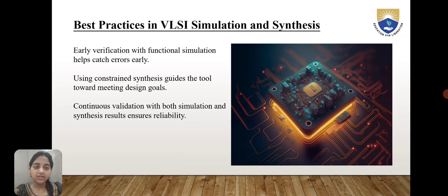Best practices in VLSI simulation and synthesis. Early verification with functional simulation helps catch errors early. Using constraints in synthesis guides the tool toward meeting design goals. Continuous validation with both simulation and synthesis results ensures reliability.